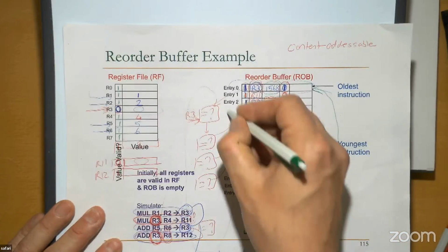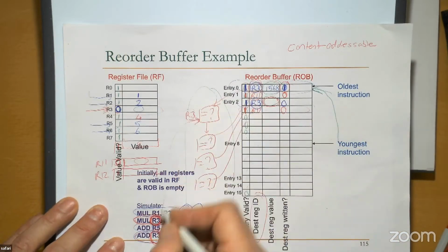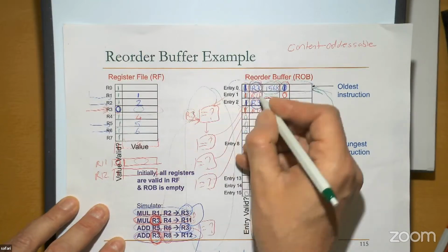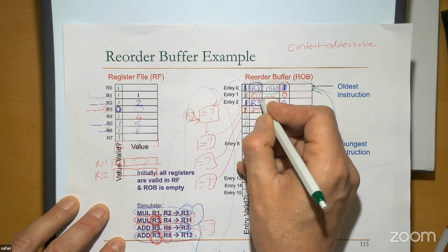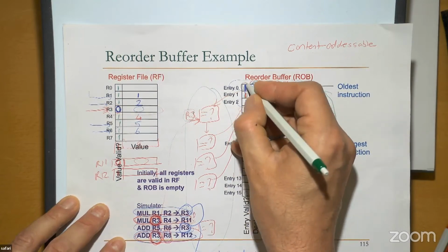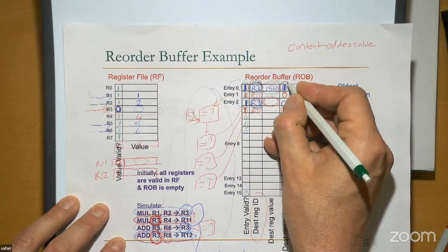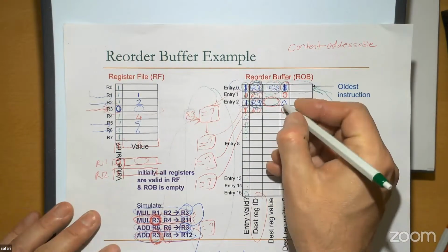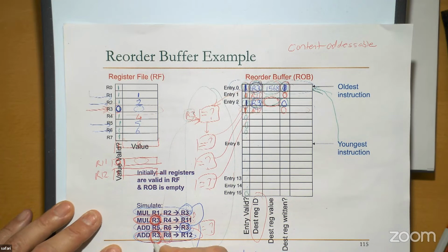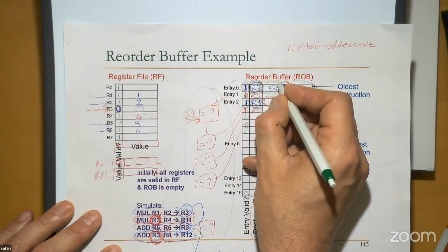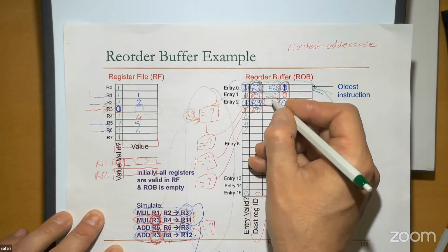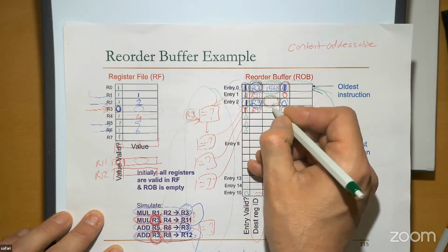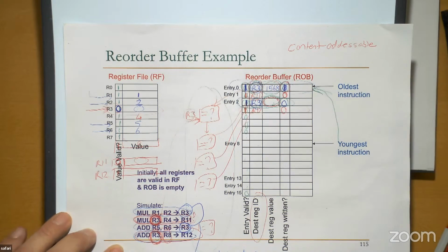Well, that's the content addressable memory, that's age-based. Whenever you compare this R3 value to every single location, there will be 2 matches. These 2 will match, and their entries are valid. This is valid, we just made it valid earlier. This is invalid. This instruction should not get the value from here, because semantically that's wrong. It should get the value from the youngest instruction that's older than this instruction, which is this one defining R3. So there needs to be logic to ensure that. And that makes this content addressable search extremely expensive. That's why we're going to eliminate it in the next slide.